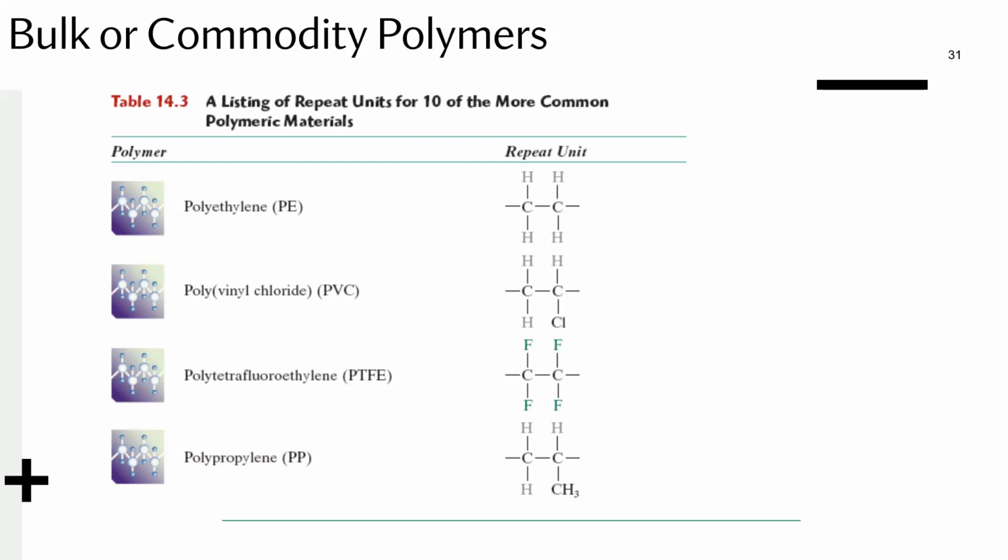And then you've got polypropylene, and you saw how polypropylene and polyethylene differ in terms of their chemical resistance. And the only difference is really that CH3 group that's replacing a hydrogen on polyethylene. So we kind of saw how a tiny structural change can completely change the behavior of these materials.